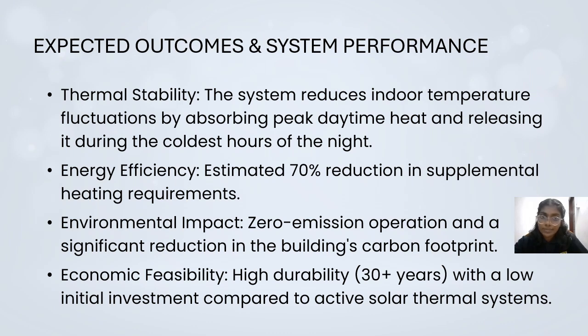The proposed system provides several important benefits. First, it improves thermal stability by reducing indoor temperature fluctuation. The wall absorbs excess daytime heat and releases it gradually during the night. And secondly, the system significantly improves energy efficiency. Our analysis estimates up to a 70% reduction in supplemental heating requirements.